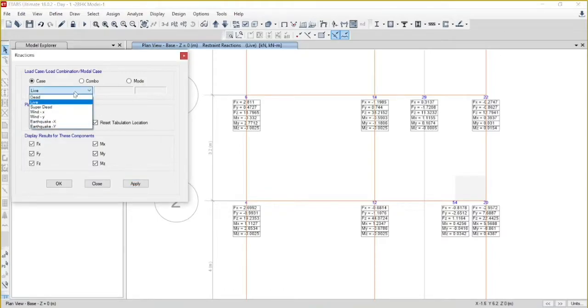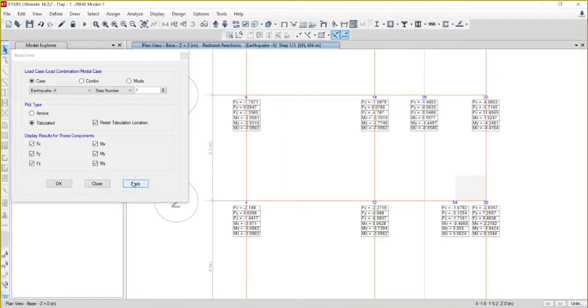And if you apply earthquake load, now we are interested in knowing earthquake load. You can see that when you apply earthquake load, earthquake is a lateral force, not a vertical force. Hence you can see that in f of x direction, you have an earthquake force of 1.75 kilonewton which is acting horizontally. And here is the maximum 2.27 kilonewton of force which is acting in x direction.